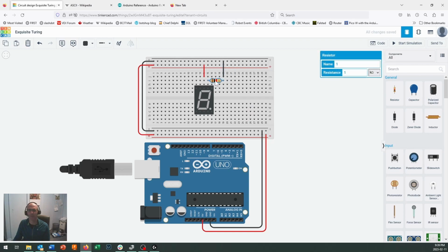Let's come in here. If you click on that resistor, okay, right clicking doesn't give you the copy and paste command, but you can come in here, and I can't remember if there's a command right along the top here or not. Copy, there you go. Control C works as well, but when you've got it highlighted, hit copy, and there's your paste. Control V works for that as well. I'll be using Control C and Control V a lot, but if that's not working on your computer, there it is right up there, and I can paste that in.